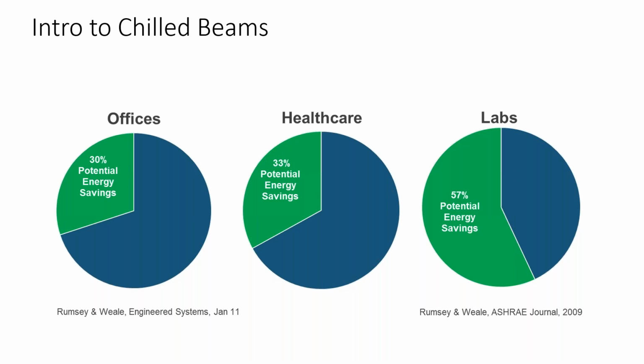There's a number of considerations there. If you have a lot of fume hoods, that can be complicated, but just make sure you're not disrupting the fume hood design, or if it's a teaching lab with one fume hood or a lot fewer fume hoods, that there are no air collisions between the beams if you have a lot of ceiling space taken up by them.